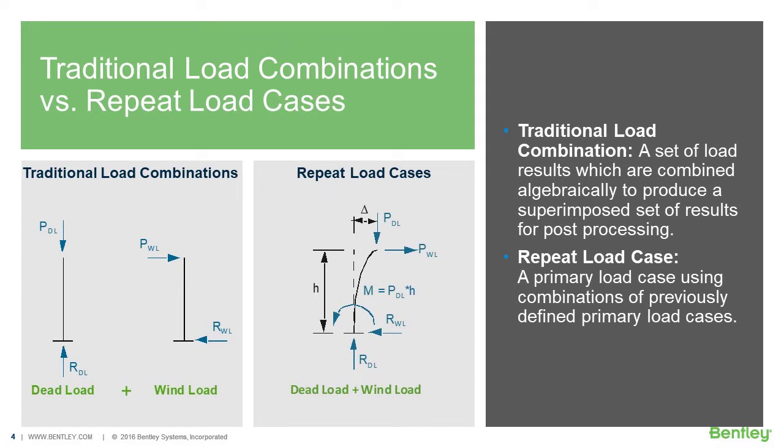In contrast to that, a repeat load case is a primary load case using combinations of previously defined primary load cases. In a repeat load case, STAAD.Pro will apply the load cases to the structure simultaneously and then calculate their combined results. Of course, this is super important if you're doing any type of second order analysis within STAAD.Pro.